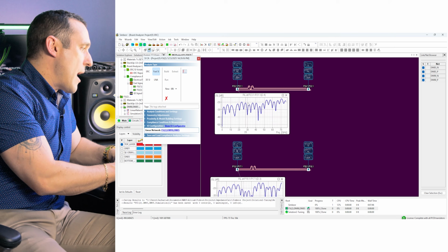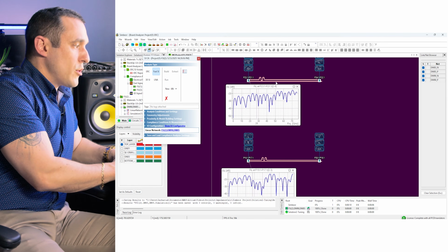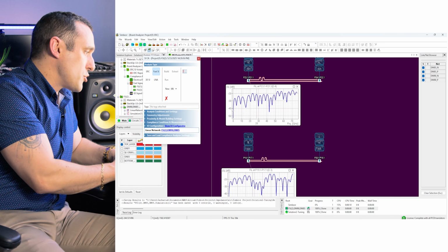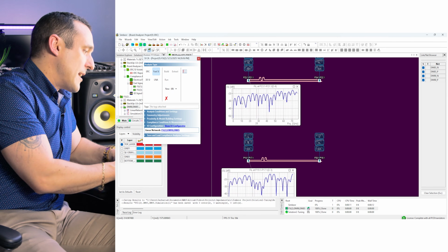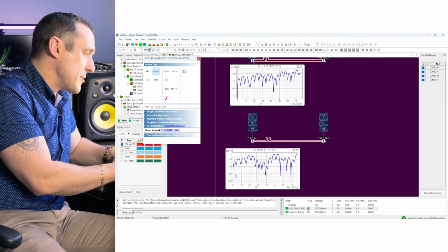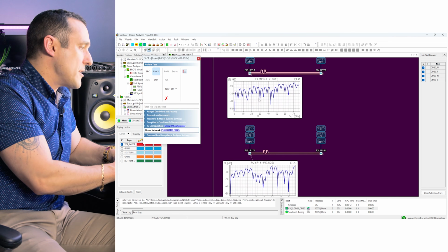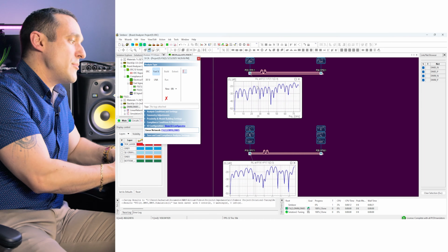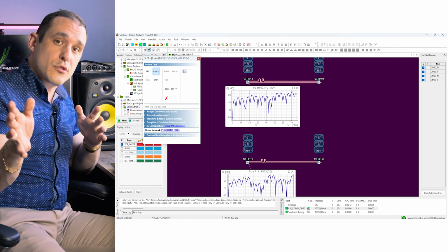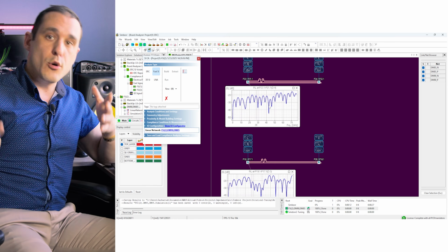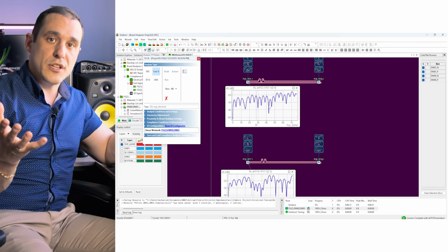Same thing here when you have the wider spacing, but it's not as dramatic. You can see that when we start with wider spacing in between these microstrips, we do get the increase in loss, but again, it's not as dramatic. You can see in the lower graph, we do rise above that negative 20 dB return loss mark before 10 gigahertz, whereas here, we don't get to negative 20 dB return loss until after 20 gigahertz. So that illustrates one solution to help prevent mode conversion in differential interconnects that require length tuning sections.